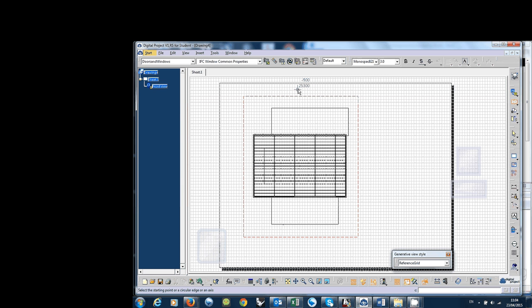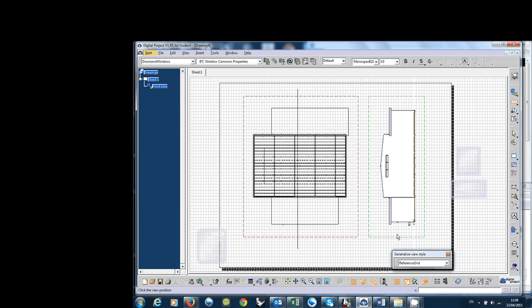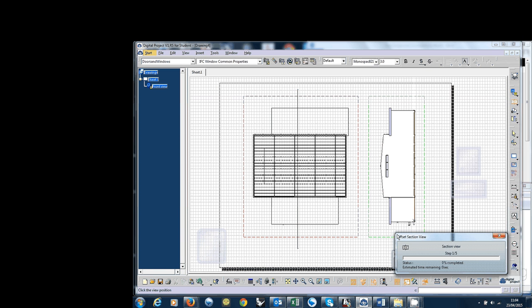So I can entirely operate on the draft. This is introducing the cutting line, and if you're happy with the location, you just double click, and then once you move your mouse out of the frame, it shows you the orientation, right? So depending on which way you look at it. Right? So if you're happy with this orientation, just left click.